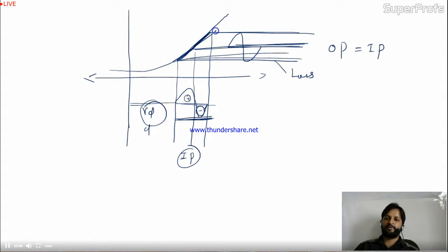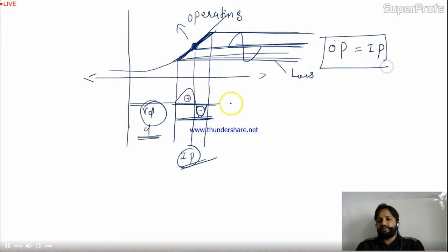If you have chosen this point appropriately, the proper point you have to choose. This point we call the operating point. Later we'll discuss it. But this is kind of, we are adding some DC part into the small signal or AC signal, so we can shift the level. If we can shift the level, the signal comes to this linear region, and once the input signal is in the linear region, the input and output mappings are equal to each other. Is it okay?